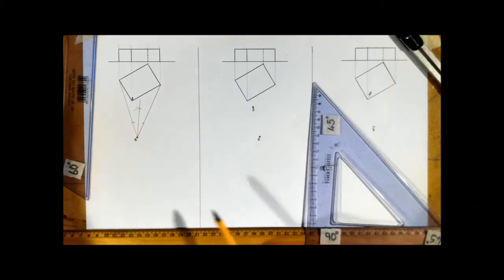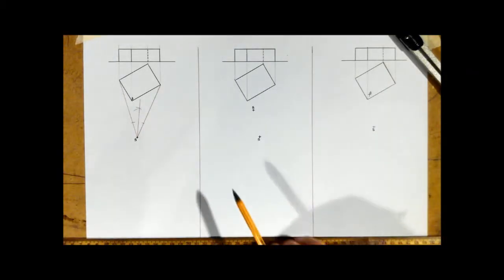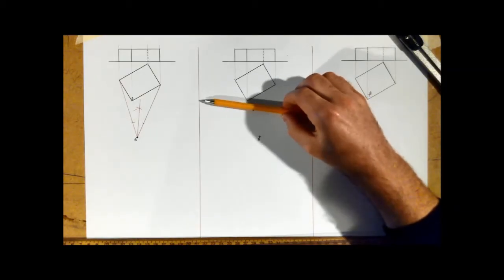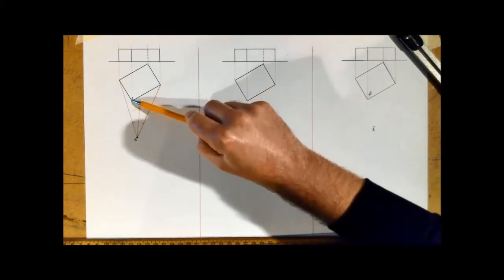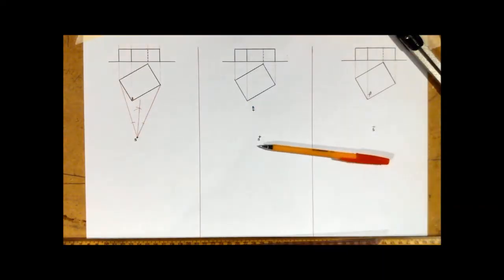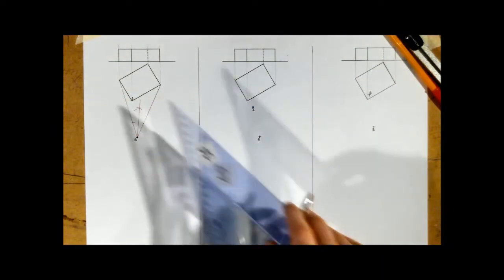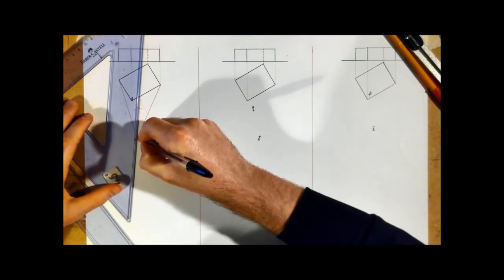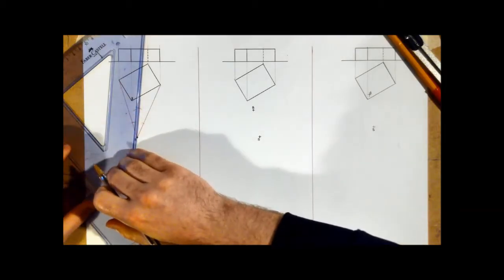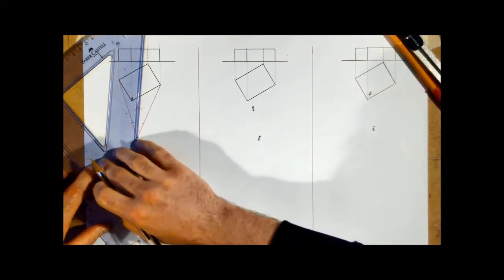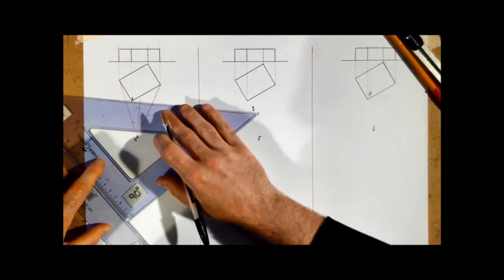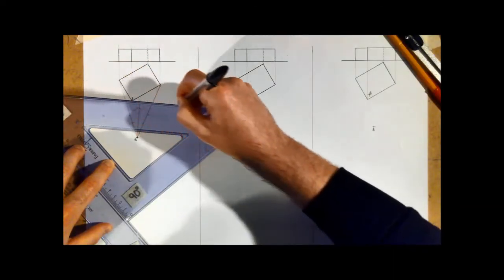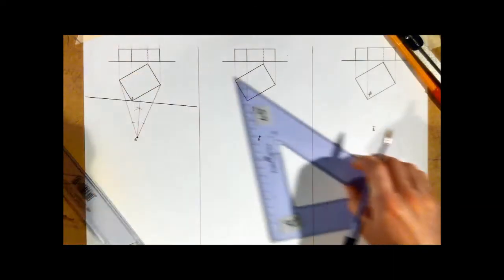And in this case, in the question here, I am saying that for the question to be completed, we have to create a picture plane that is passing through the corner A, and we can see corner A is right on the corner of our box. So to set up the picture plane, it's just a little bit of sliding set squares. Often what I do is set up my 45 degrees long edge on the line of sight, put my 30-60 underneath it, and then rotate to the left. And passing through the corner A, I'm going to set up what's known as a picture plane.